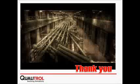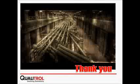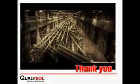No. For time of flight, you would have to bring out an oscilloscope to get the measurement of exactly where the failure is. From my experience with most customers, the localization is enough to determine where the PD is occurring, and so you can decide whether the GIS must be opened or not. But with the sensors installed, you can add the oscilloscope and do the time of flight. That will be something apart. With our antennas, you can perform it. Okay.